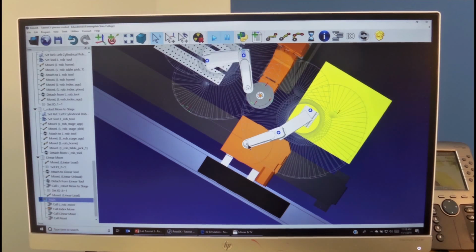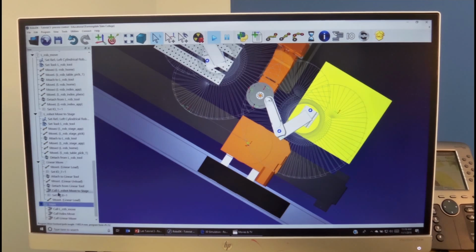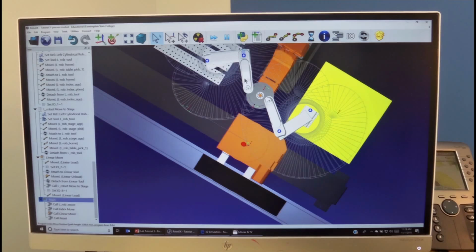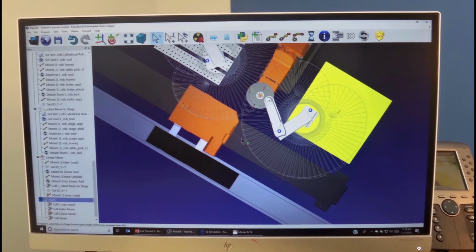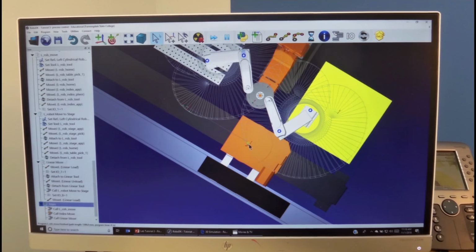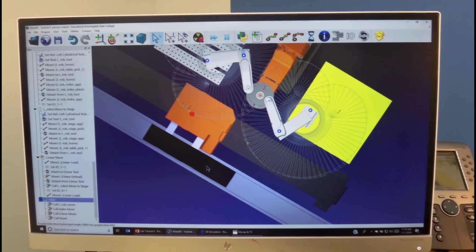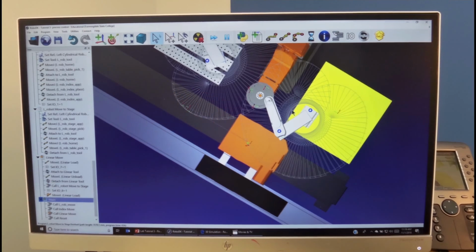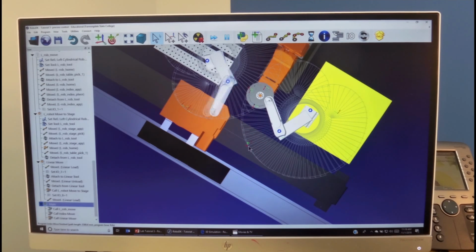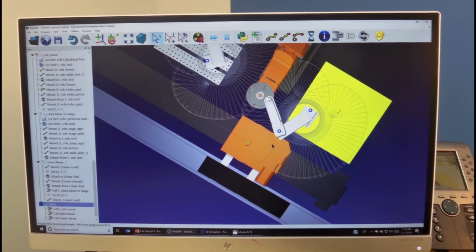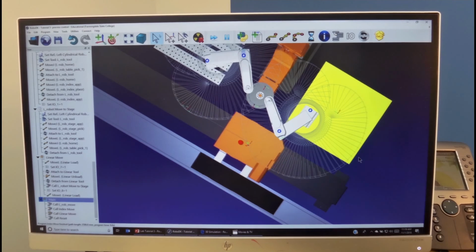And what we see here is that the pick position of the robot is actually the place position here and the pick position here when we write the software is right at the edge of the work envelope. And this means that it is recommended to move the linear stage towards the robots in order to move the place and pick positions from the periphery of the environment.